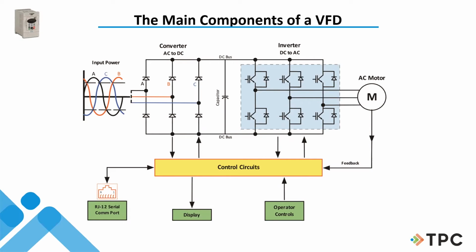So it's important that you know what it's supposed to be, because if you don't know what it's supposed to be, then whatever it tells you, how are we going to know that it's right or wrong? So keep your drive manuals handy. And one thing I would tell you is sometimes the parameters, settings, and numbers change with new versions of drives. So make sure that the manual you have is for the drive that you're working on. They may look the same, but internally they may have made some changes. So always need those drive manuals. They're very important to you.